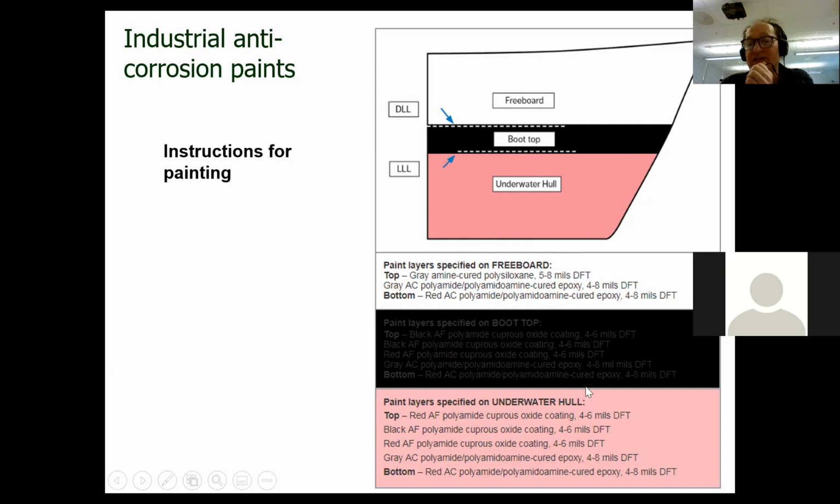And just to take the pink part in a little bit more detail, what we actually want to try to do when we're painting the underside of a boat, apart from giving it corrosion protection, we also want to try to avoid the growth of marine creatures, especially barnacles and polyps on the submersed part of the boat, because this will cause a rough surface to appear on the boat, and it will slow down the boat when it's moving along, especially a large ship.